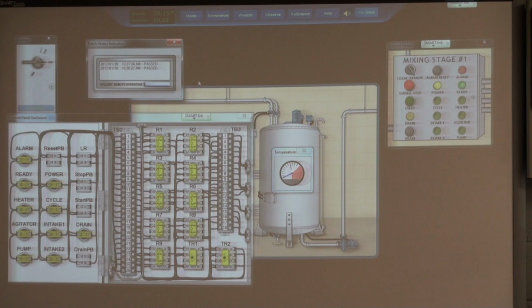We're not using the right-hand contact set, are we? Because if you look, we're not using 8, which is common. We're not using 5, which is normally closed. And we're not using 6. You're using the left side. They use 2 and 7, the coil. Remember coil versus contacts. I know some of those don't know.